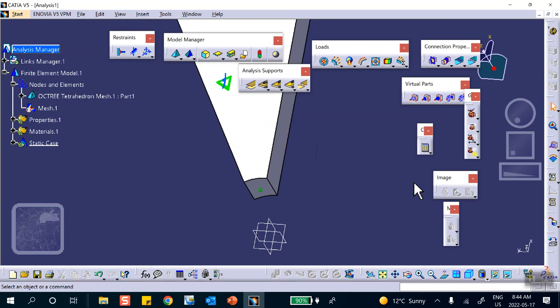So there is nothing magic about a plane of symmetry. All that means is that things on that plane do not move perpendicular to it. That's all. So instead of using a surface slider, if I took one of these surfaces and said nothing moves perpendicular to it, that'll do the job. I don't need a surface slider. It's the same thing. And that's very easy to do on this one. Of course, you can go ahead and put a surface slider there. Okay, you can do that, no problem.